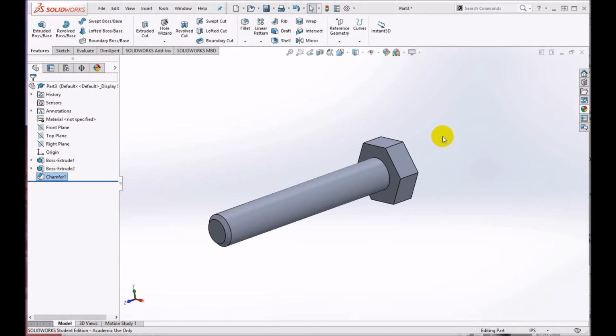When you are working with SolidWorks, you'll notice that, for example, I'll look at the sketches that are in these various features, and this one right here, this sketch, which is the circle, we want to have that circle be available for the helix, but it is consumed by the extrude operation. Thankfully, in SolidWorks, you can derive a new sketch from an existing sketch and use that for future operations. I will demonstrate how to do that right now.